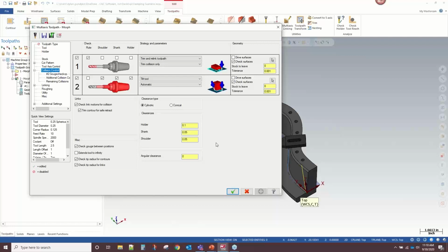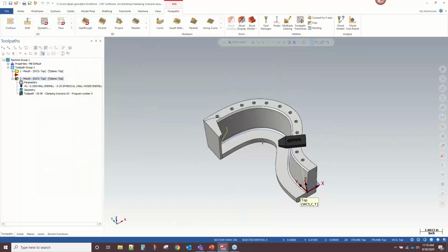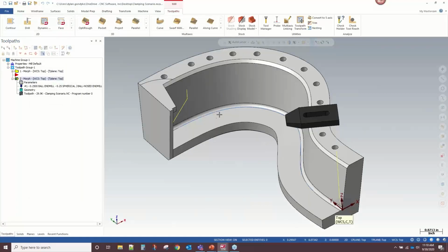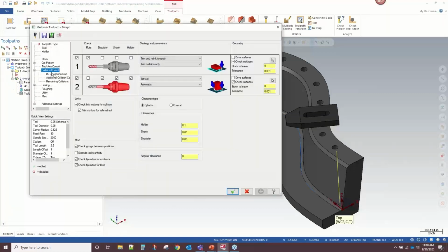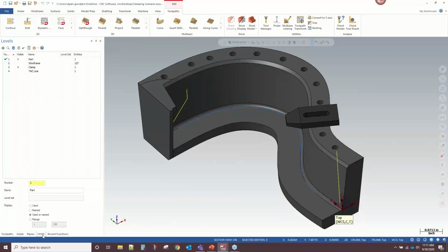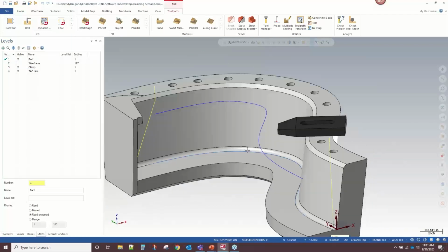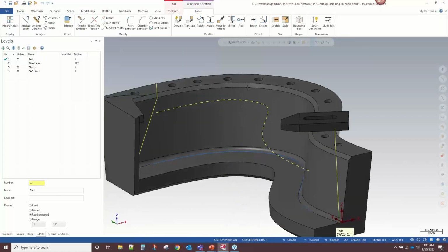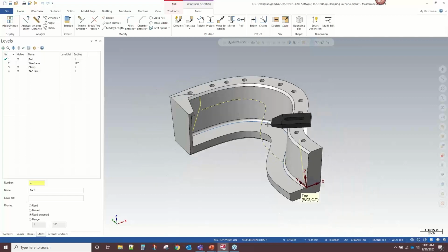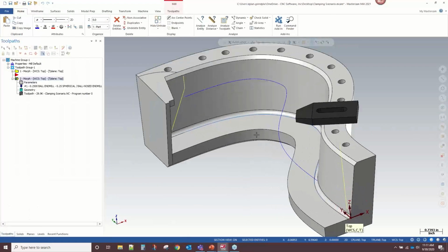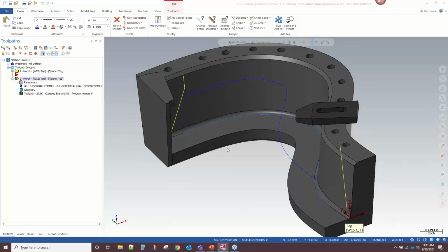So how can I drive this a little smarter and build the intelligence of that clean motion into the tool axis control strategy rather than this collision control calculation at the end? Well, for this one, it's going to be a piece of wireframe, as I imagine you could have predicted. And I've just made this spline on level 4 here, tool axis control line, and it's literally just an offset of a wireframe edge of the top of this part. And I want to use this to drive the motion in this path. So I'll jump into this morph,